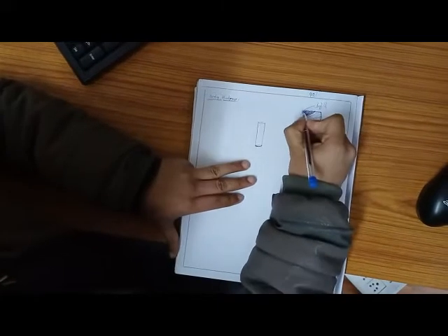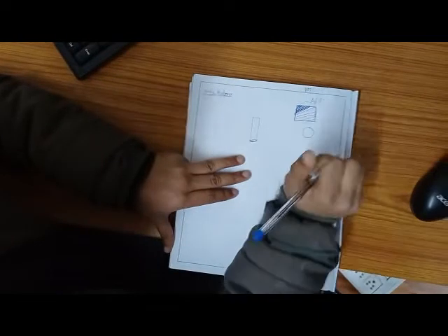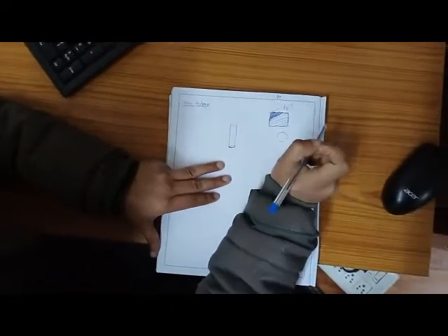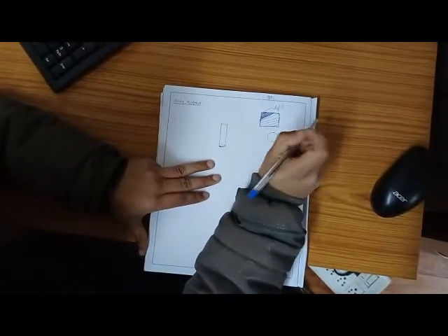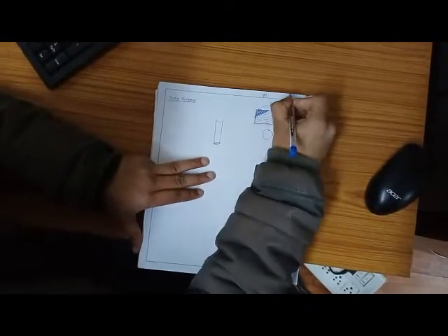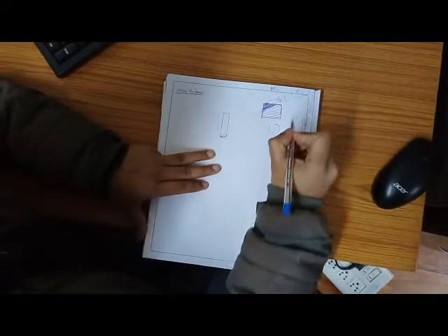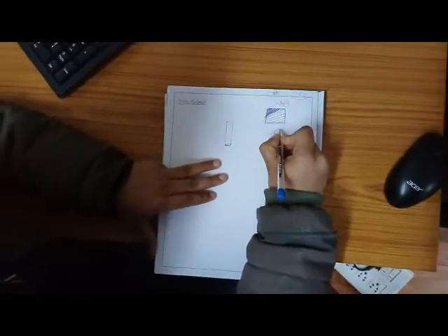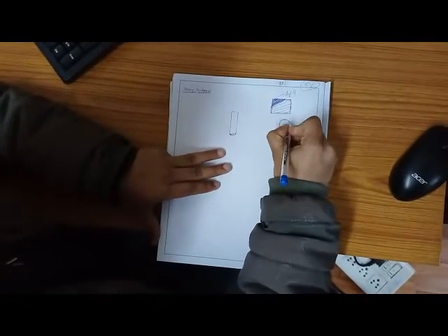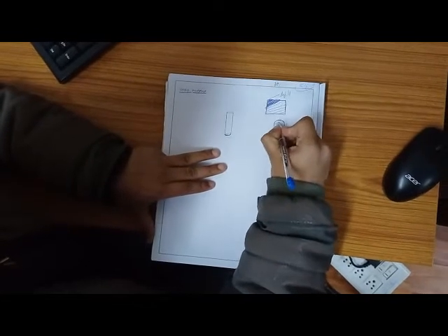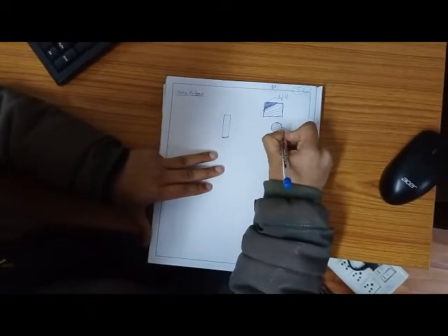Fine, so even very minute locations it will try to fill with the ABS material or ASA material, the printing material. If you are giving 5%, suppose this is the 5% infill density, what it will do is first of all make the border, this is the boundary it will make. After that, it will simply print in this way.